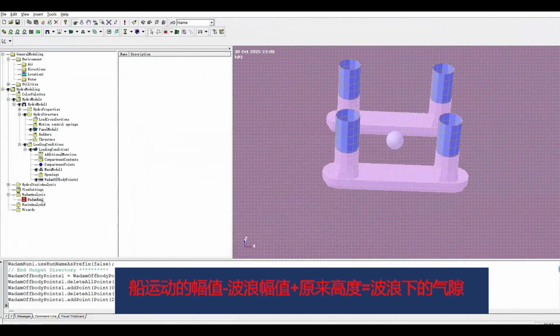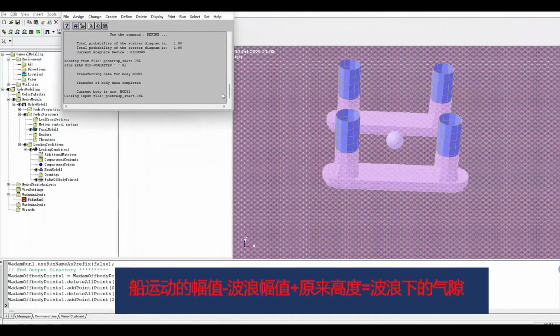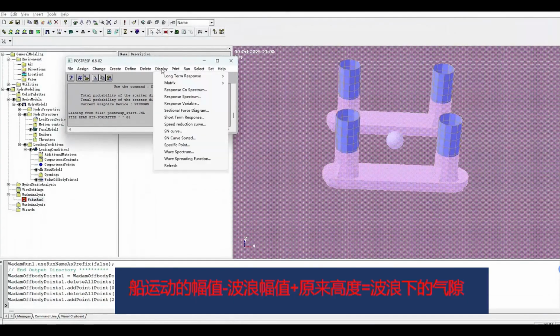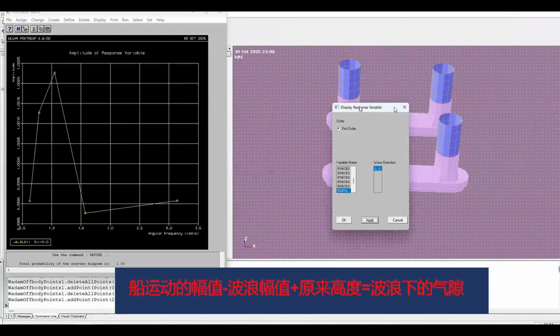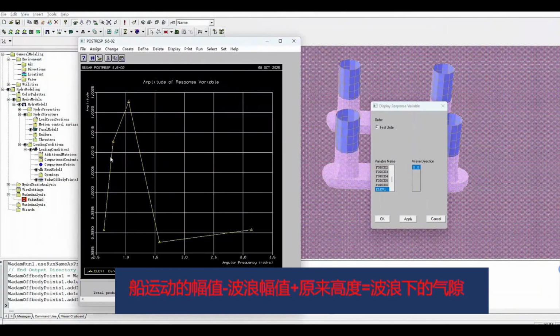The simulation is finished. Now let's take another look. Print out the variable from just now again. The elev variable. Alright, at this point we'll notice that although the shape still fluctuates up and down, the values on the y-axis are between 0.999 and 1.002, very close to 1. Why is that? That's because what it's outputting is the elevation at that x, y point in the global coordinate system.